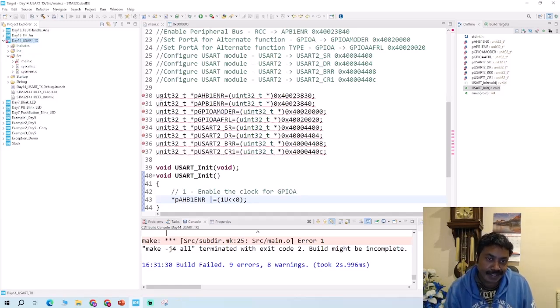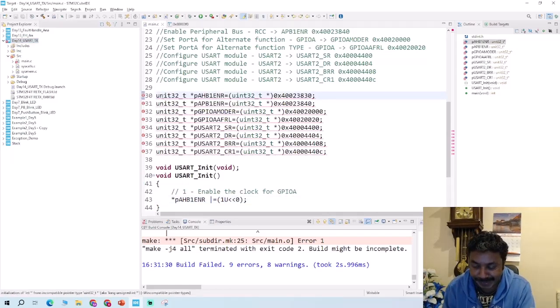See, the pointer declaration, the compiler doesn't know what type it is, because I made a simple typing error. Instead of uint, unsigned int, I typed unit. Because I copied 8 times, it's throwing 8 warnings followed by a link error. So I've got to go and fix it, which I'll show. It's uint and uint, not unit, uint.